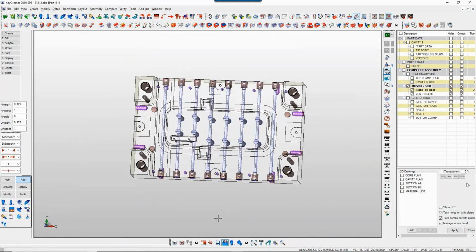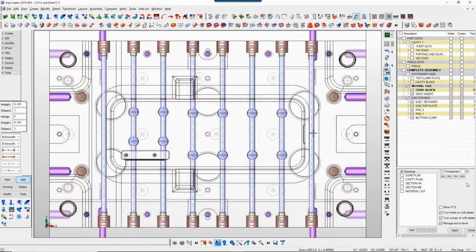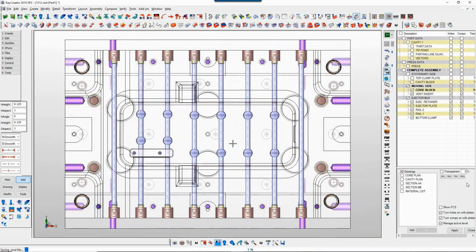Okay, so really easy. Your ability to try something out and then try something else and do different scenarios really quickly allows you to make the perfect mold design much, much easier. We have meetings with customers all the time, and we're able to make changes on the fly right in the meetings instead of having to wait and do the changes after. So our customers can see us move ejector pins around, switch water locations, tip them, and modify bubbler depths and things like that. So there's a lot of things you can do very, very automatically.